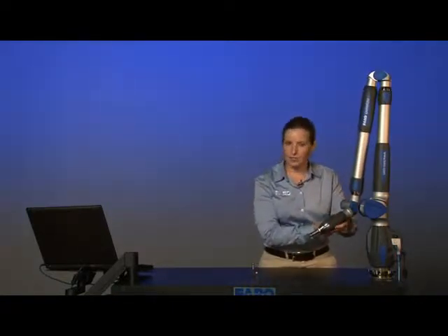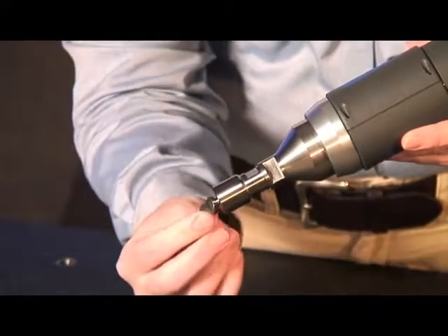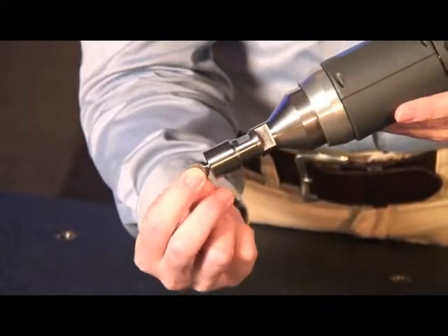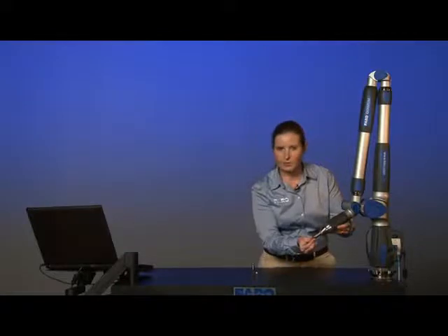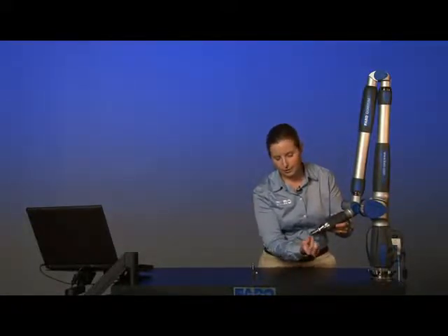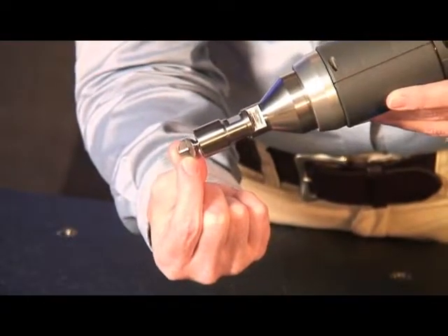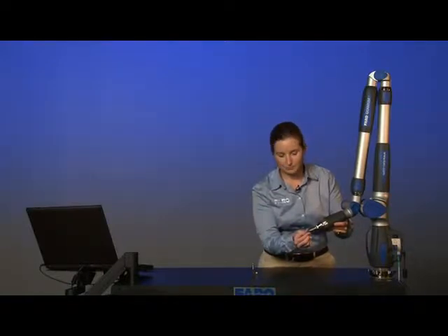What we have attached to the end of the arm is a swivel probe. And this particular one, you can see that the ball pivots on the end of the probe and it has a cutout in it. And the cutout goes exactly to ball center. So as you're gathering data, your part is going to ride at the middle of this probe to capture your data. And there's no need to adjust for the radius of the probe after you capture that data.